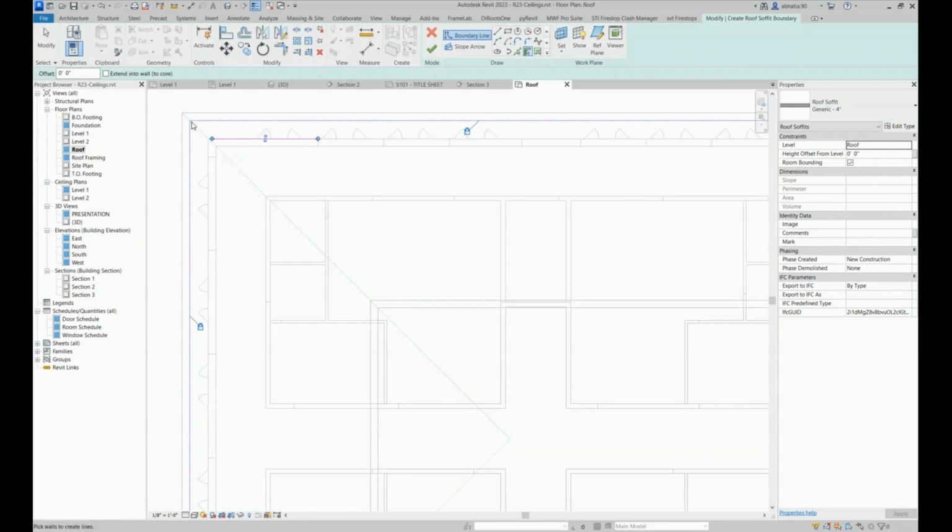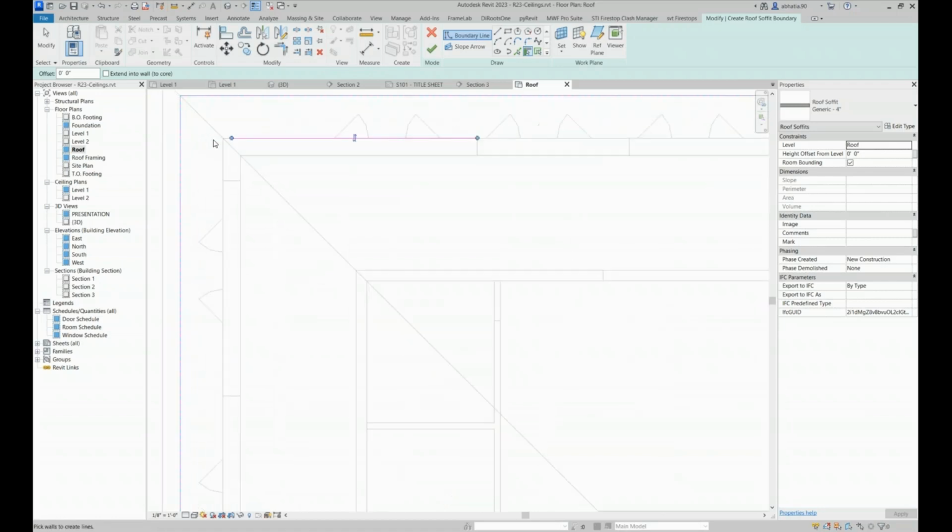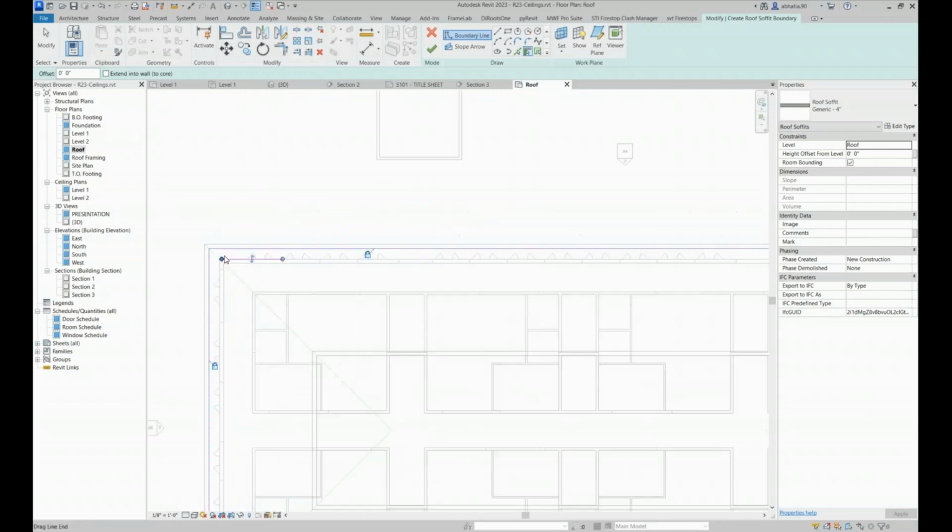Because this might take precedence maybe over this one, you won't have a diagonal here. You might have it as a solid cut. So this might go all the way through, and then there'll be another piece being placed here. So you'll have multiple panels most probably because you want the members to go in the shorter direction, right? So you want the span to be in the shorter direction. Whereas if you treat that all as one panel, you will have all the members facing the same way, or the span will be in the same direction.